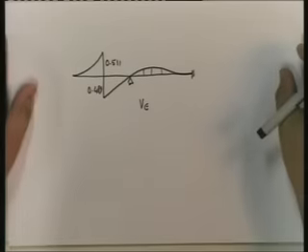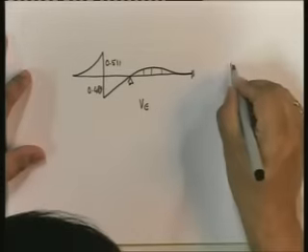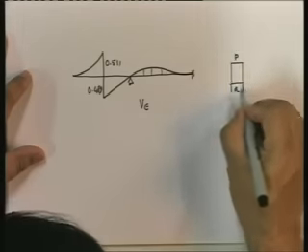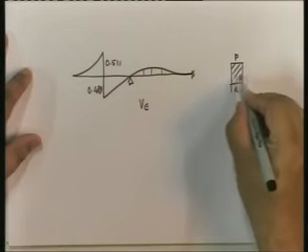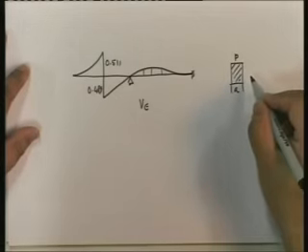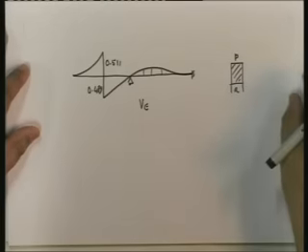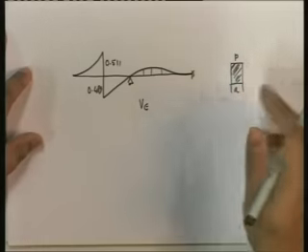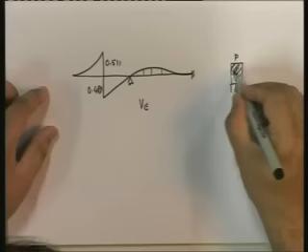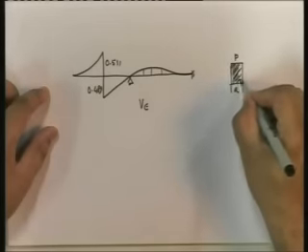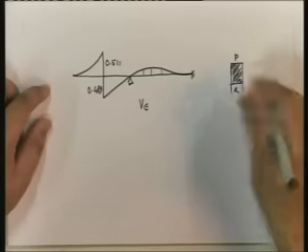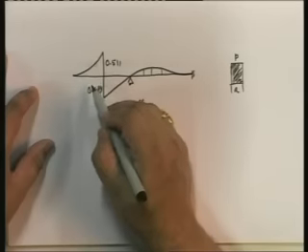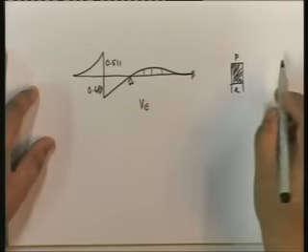Now the point here is, if we have a load which has a particular pressure over a particular area, this is a typical class AA loading, 70R loading. If you look at the Indian Road Congress Code, IRC 6, you will see that you are given this kind of load. Of course, what you are given is many loads together. But the point is that once you have one load position, you have all the other load positions automatically.